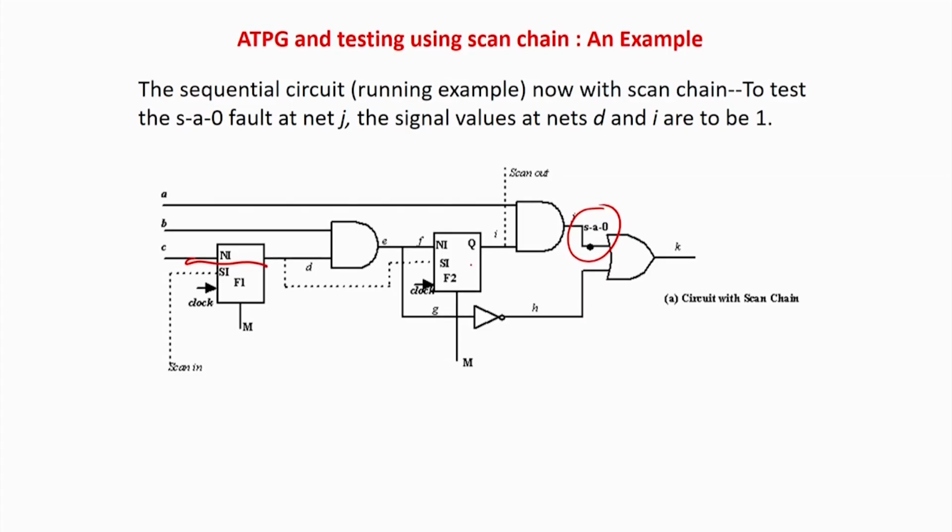So I just say that there are no flip flops over here. Just assume that they are directly connected. For timing you just assume that. So I am making a pure combinational circuit by removing all the flip flops, connecting the input to the output, and your job is done. Then go for combinational ATPG.